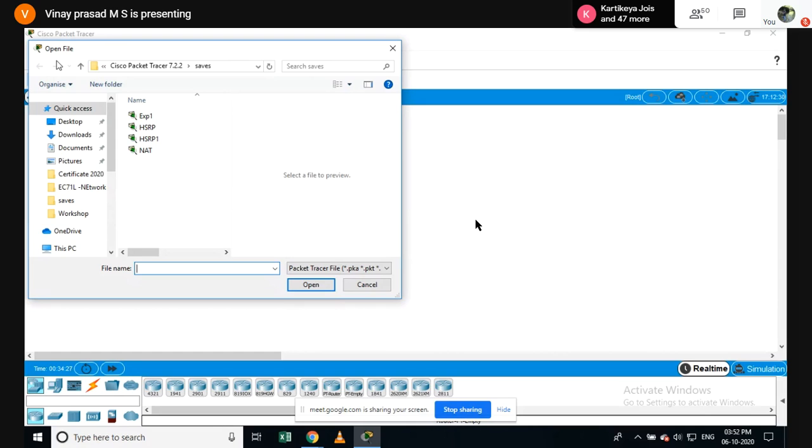Similarly, we have tools where you upload your layout diagram and mark wherever you have a closed wall and what kind of wall it is. Based on this input, the software is able to understand what kind of attenuation can come across in that location.